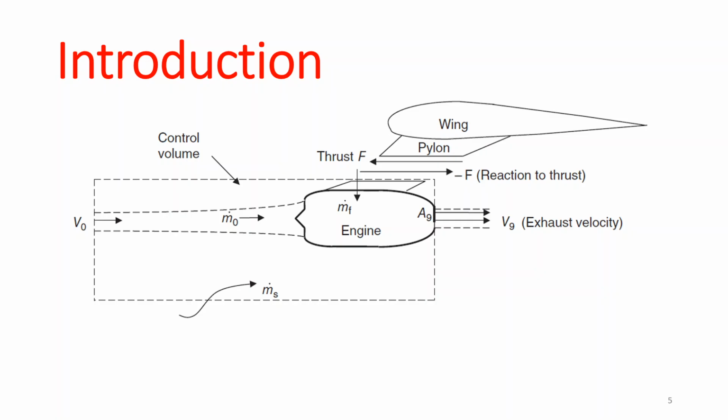If we have the jet engine as the control volume, then you have to calculate and include the forces applied to the fluid by the walls of the jet. That would be a more complicated step, which we will talk about later on. And then we couldn't have used the inlet, and that would be very complicated.